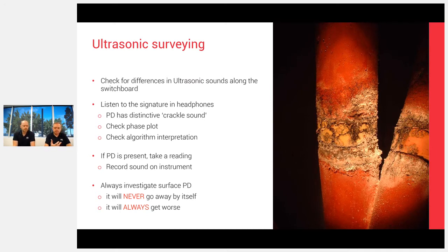Surface discharge. That's a new one. Haven't heard it called that before. No, but surface PD, it won't go away. It will always get worse. It's a cumulative effect as it degrades. So once you've got it, really, we need to start investigating that. Yeah.